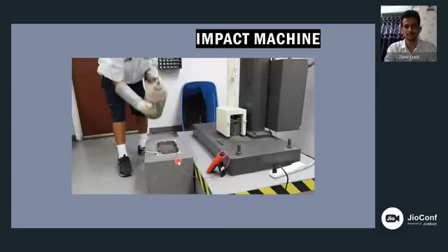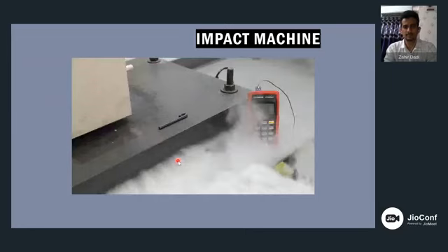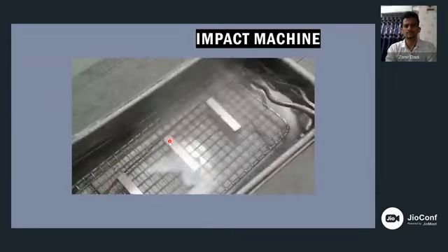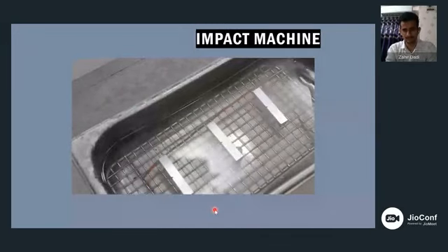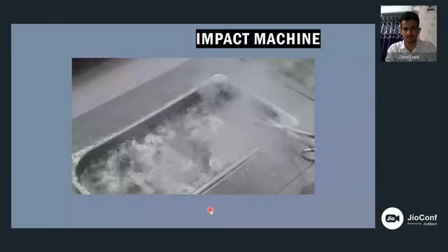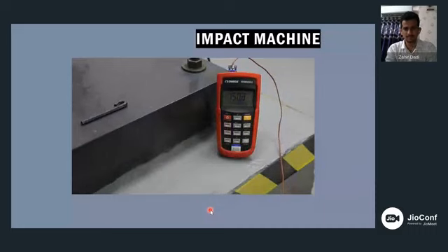Depending on the type of material, the specimen can be tested at between an ambient atmosphere and minus 150 degrees Fahrenheit. The sample piece is an ASTM A320 L7 stud, which requires the testing to be conducted at minus 150 degrees Fahrenheit. Once the required temperature is obtained, the specimen is held for a measured period of 5 minutes.